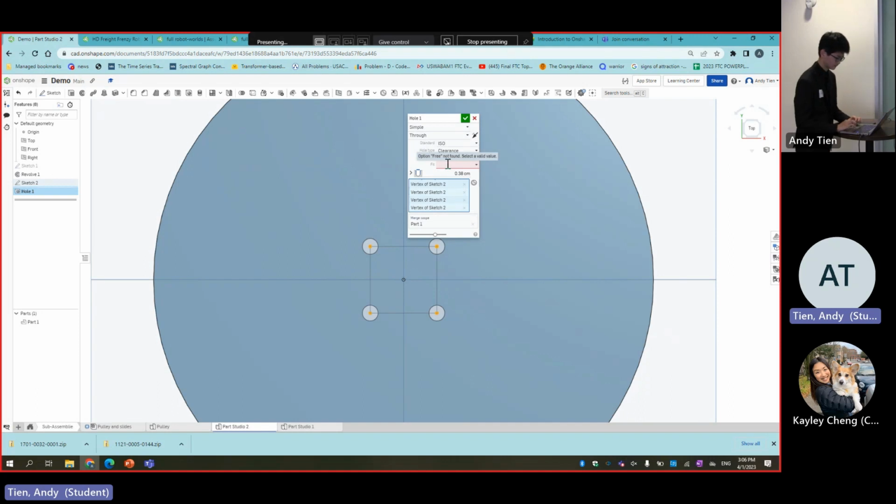And then you can see this is fit. So what does fit mean? Fit is basically how well a part or two parts will mesh together. There's normal, loose, and close. Close is kind of like a press fit, so it's going to be really hard to put together. Normal gives you a little tolerance. And loose is basically where your part can still wobble around in the hole that you made. So in this case, I'm going to go with normal.